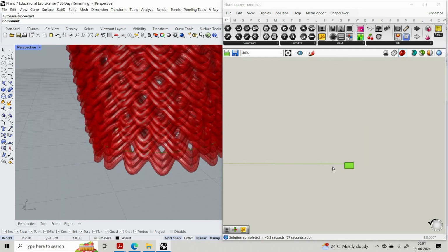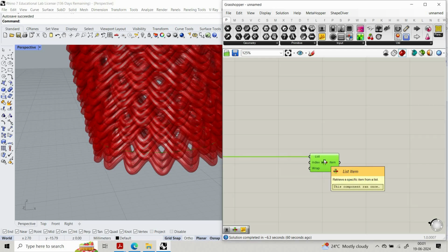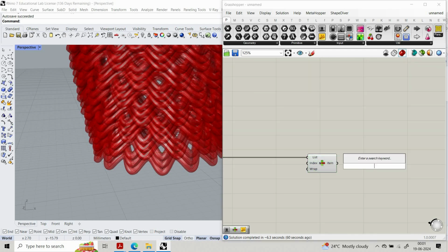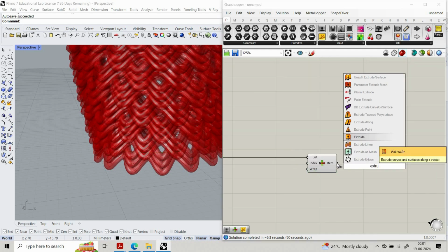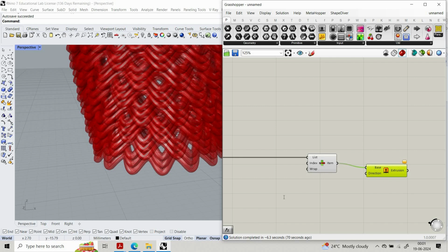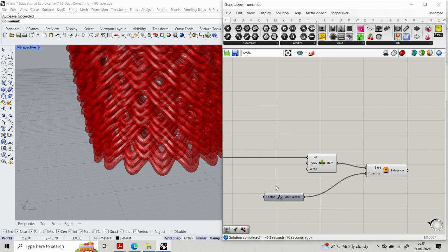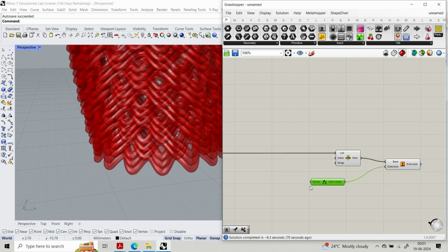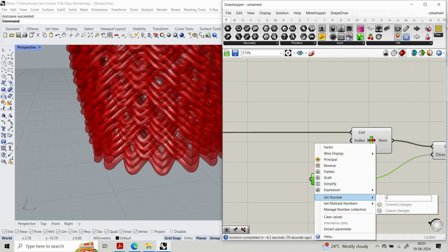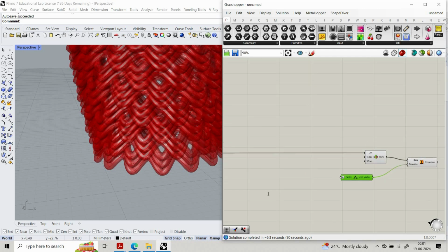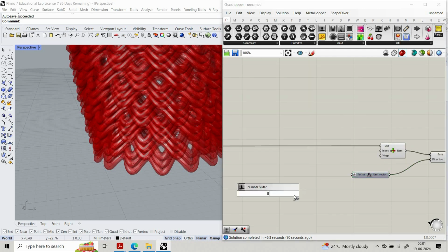You see this curve is being selected. So I'm going to extrude this curve in unit set, but obviously in the downward direction, not upward. So I'm going to use -6, -x, and maybe why not 8.